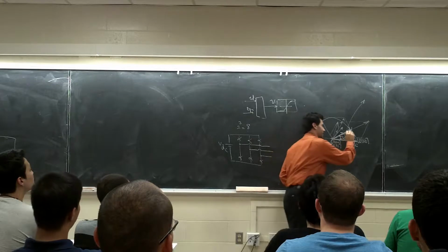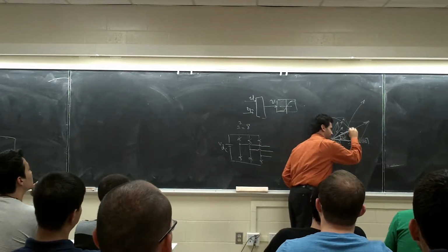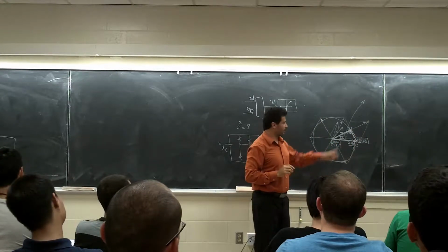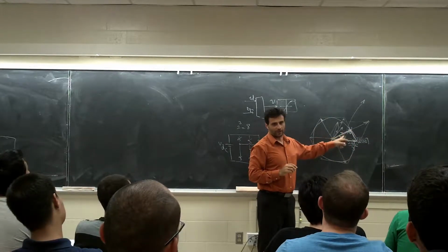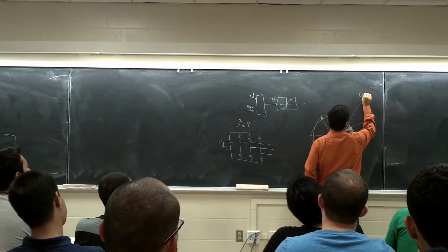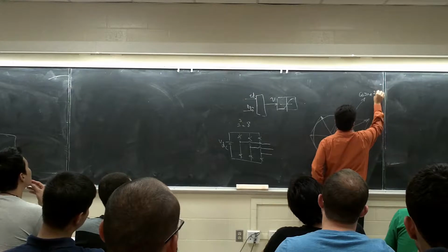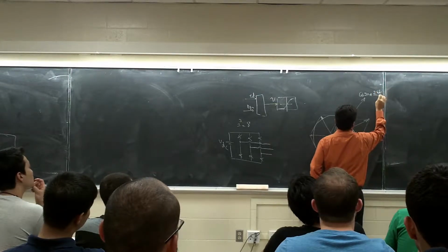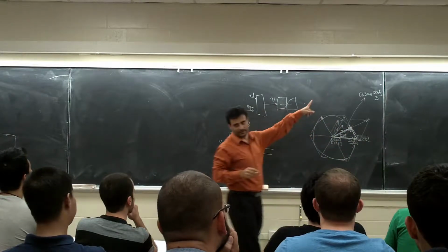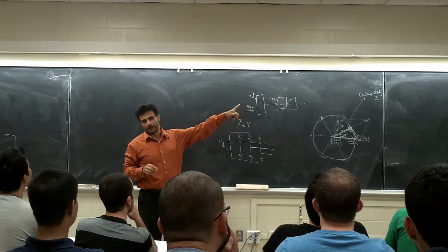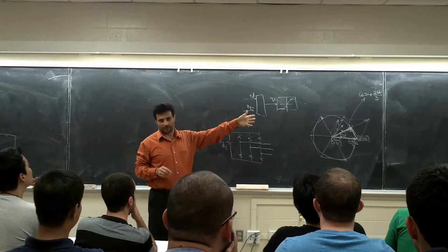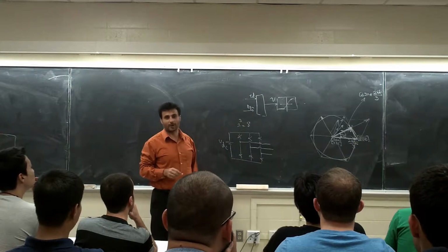30 degree. And based on the hexagon, if you connect these two, this one is going to be perpendicular to this one, right? So how much is this one? Cosine of 30 times this vector, right? It is cosine of 30 times 2 over 3 VDC. This is the maximum phase voltage in the space vector.